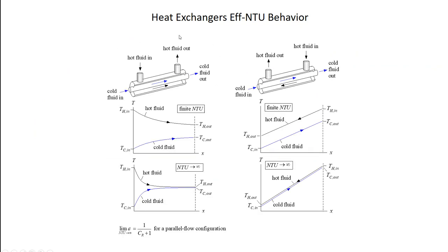So here is a counterflow heat exchanger, and right next to it I have sketched up a parallel flow heat exchanger, right? And we're going to look at this in the situation where the capacitance ratio is equal to 1. So I'm away from that very unbalanced limit. Configuration should matter. And we're also going to look at a case where the NTU is not really low, which means that I'm getting some pretty substantial temperature changes in my fluid. So what does the parallel flow temperature distribution look like in that limit?